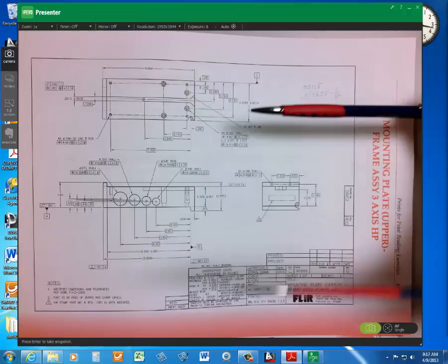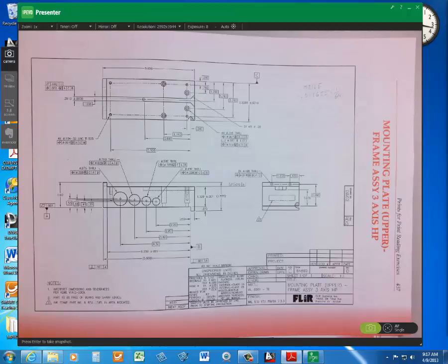Now, when you're talking about using a counterbore, what kind of fastener is going down in there? Why do we use a counterbore? What kind of fastener fits inside of a counterbore? Any idea? Okay, it wouldn't be a flathead screw. We'll X that one off. A flathead would be a countersink. So what kind of fastener goes down in there?